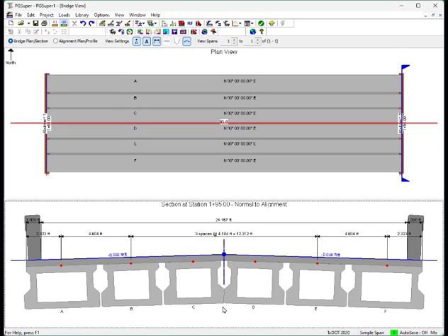I'd like to make a quick note about joint spacing and adjacently spaced beams in general. In PGSuper, girder spacing is always measured horizontally from centerline to centerline girders. When joint spacing is input, PGSuper computes the girder spacing based on the maximum width of the girder plus the joint spacing and using a small angle assumption. This means that the spacing doesn't change even if a very steep super elevation is entered. So don't necessarily think of joint spacing as the joint width at some elevation between girders.